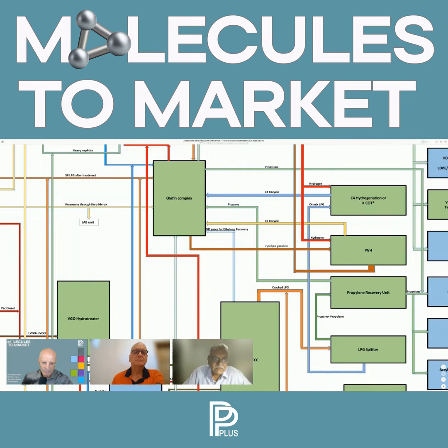And the third part is all control valves and safety valves, which are there in the plant, whichever is a part of the technology, they should all be sized. Once the process design is completed, you have the data. Whether he does it or the consultant does it, this part of the exercise should get completed. So we do all these things and incorporate the findings of all these three entities into the basic engineering package per se.